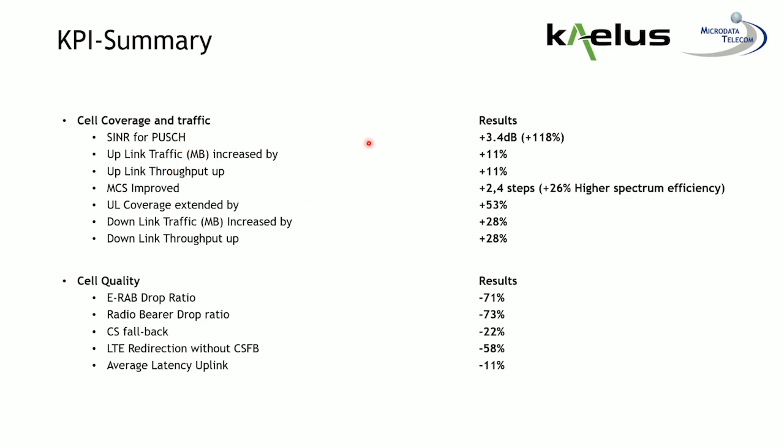from this trial shows that the uplink gain was 3.4 dB, and the jumper loss or feeder loss was about 2.5 dB, and that illustrates our typical rule of thumb that it's feeder loss plus 1 dB. That is the general gain with the TMA, because system sensitivity typically goes down to about 1.7 dB of noise figure with the TMA, and in general it's 2.8, 2.9 dB without the TMA.